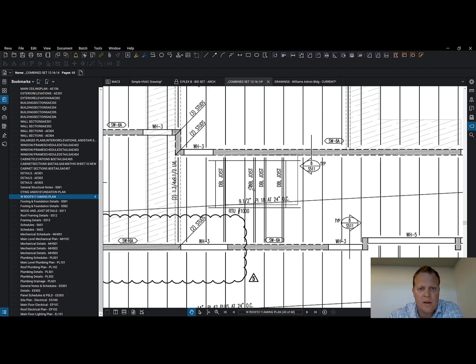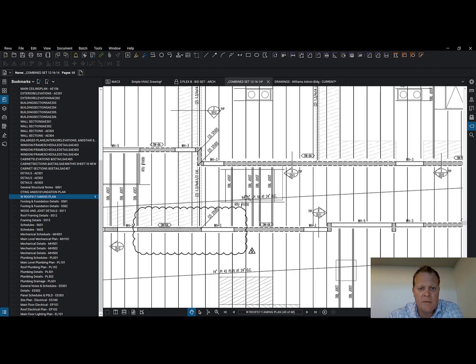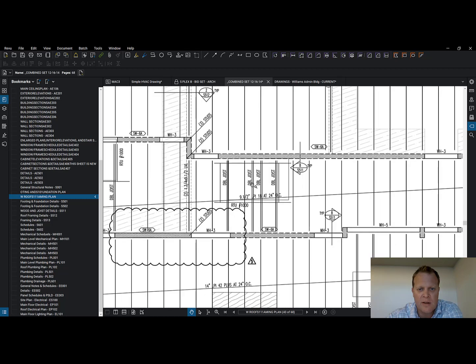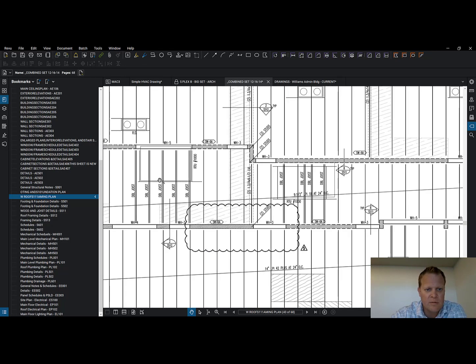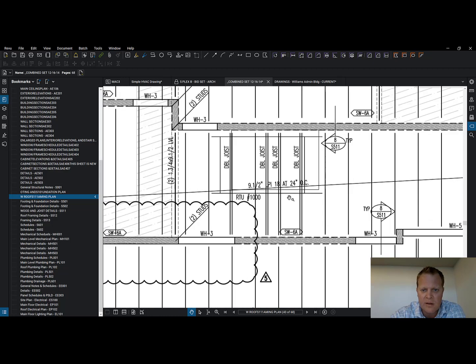Well, maybe that's something we need to make sure that the framer has for sure, because right here it looks like he's got double joist, double joist, double joist, but then it looks like to me like the spacing still carried through, and maybe this guy's actually in the way. I think we better be paying attention a little bit up on the roof for that one, because on this one, double, double, double, double, and they're spaced out. What's the spacing of that? That is 24 inches center on that.